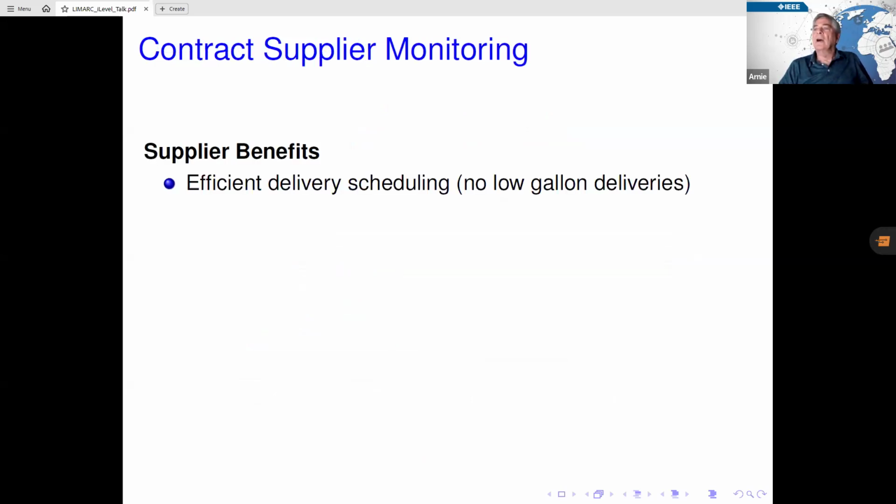So the contract supplier has to gauge what's in the residential tank without having a monitor. How do they do that? They use the numerical factor of 2 milligallons per degree day of heating, and they know how much they delivered the last time they delivered to that tank, so they know how much the ullage is, which is the unfilled portion of a tank.